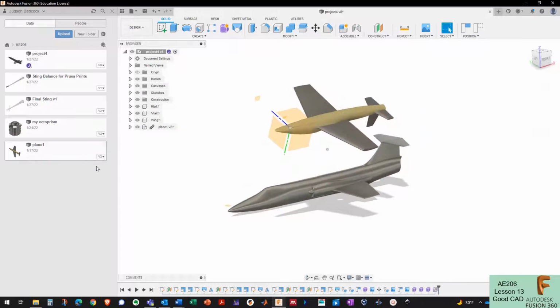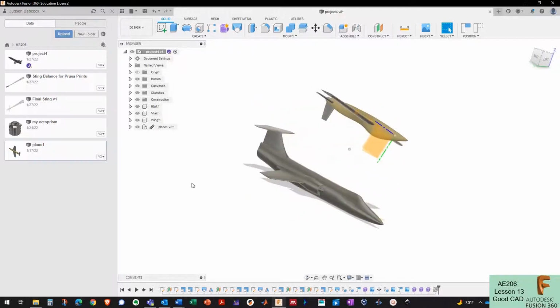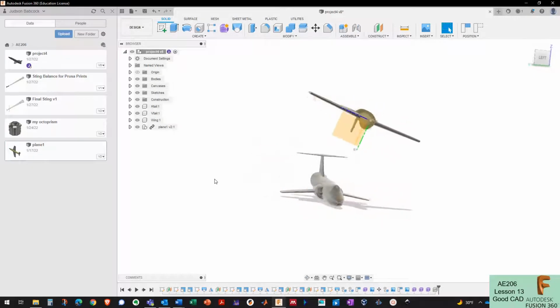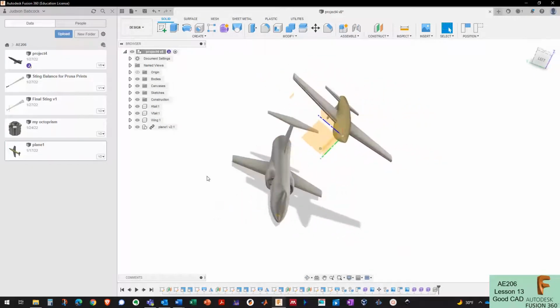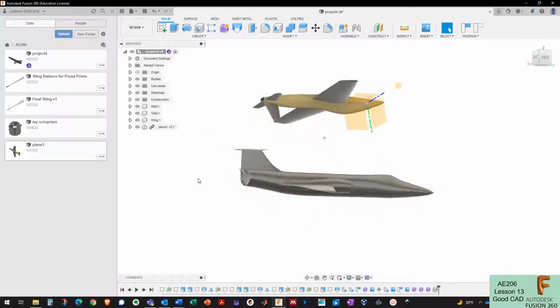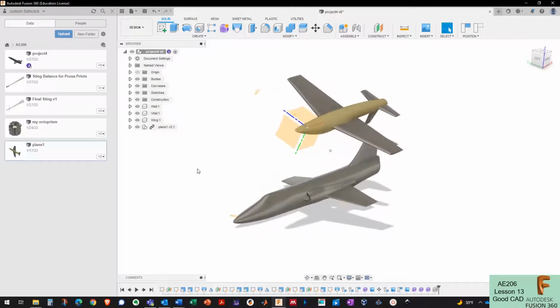Okay, the drawback to the bottom-up modeling approach is that we could have dozens or hundreds of other CAD files that we have to insert into one master CAD file to define that assembly. Links can get broken. It can be hard to track the versions of those files and changes. So the way that Fusion approaches this assembly is by offering the user another option. We can, of course, do the bottoms-up modeling where we put all these things in one file and define joints in motion,